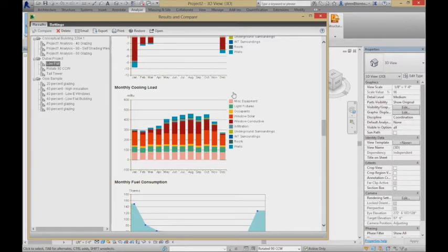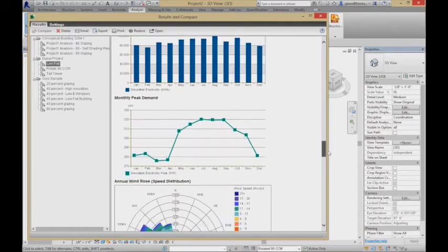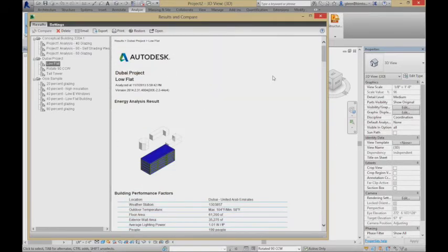In addition to the heat that comes through the window, there's solar radiation that comes through the window and heats up the floor and then actually gets absorbed inside the building. So there are two different issues. One's just kind of the thermal resistance of the windows. The other is how much solar radiation passes through the windows. And we can get windows that are optimized for each of those different things. So we definitely have room for improvement on the windows. Okay, that's enough to get going on that.